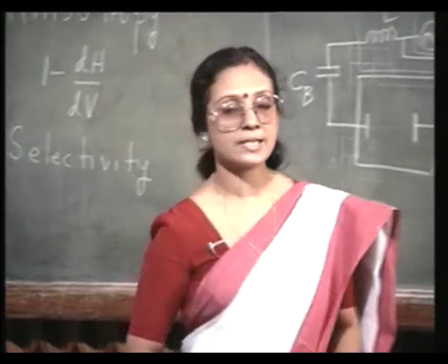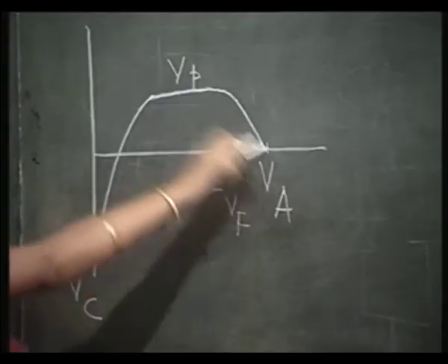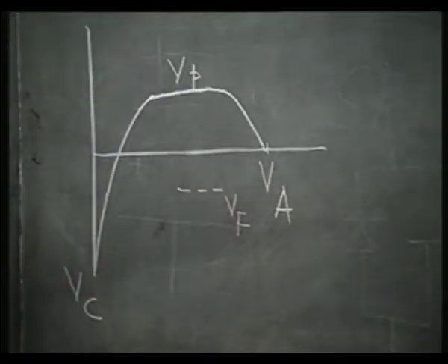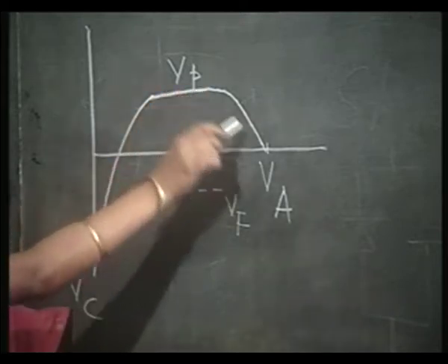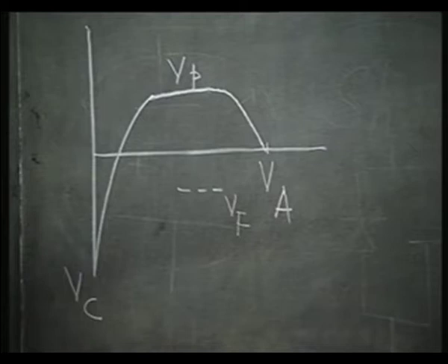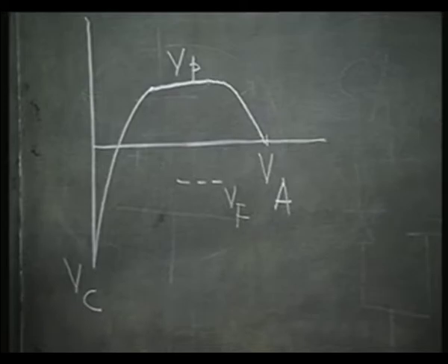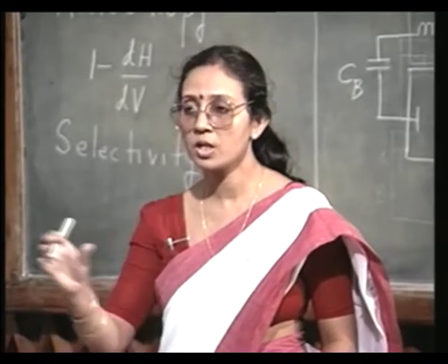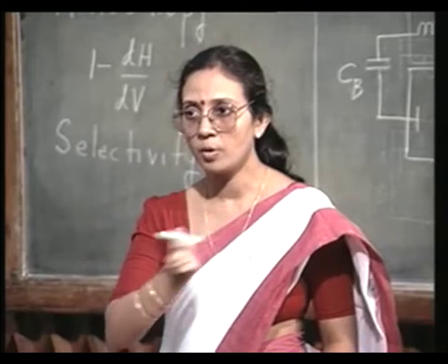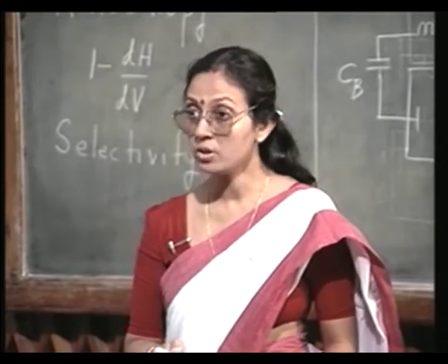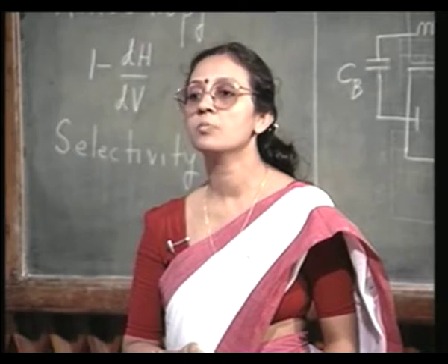So, let us say if your substrates are placed on the anode surface, it is going to experience a small ion bombardment energy because the difference in energy between Vp and Va is not very much, it is a few volts, maximum 10 or 20 volts. So, the plasma glow is at a positive potential, the anode is at 0 potential, and the bombardment will be towards the anode, yes, but with a comparatively smaller energy.